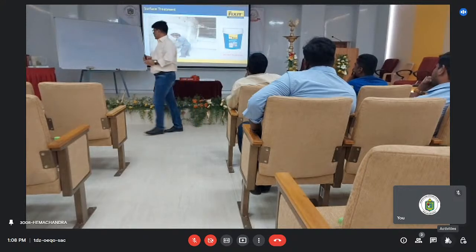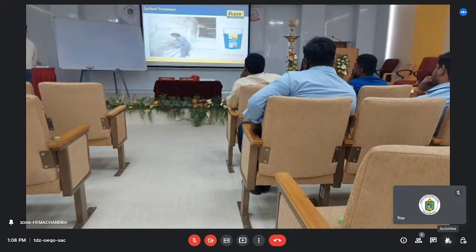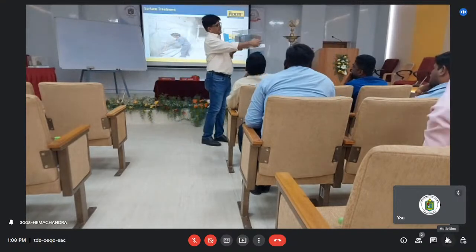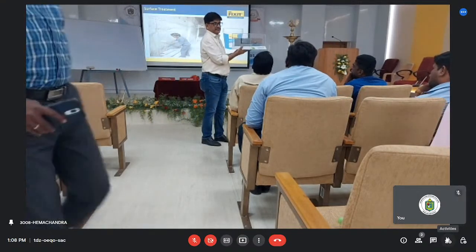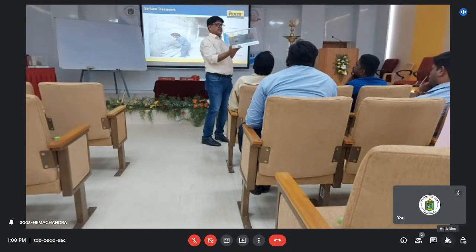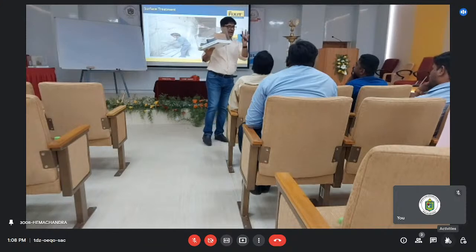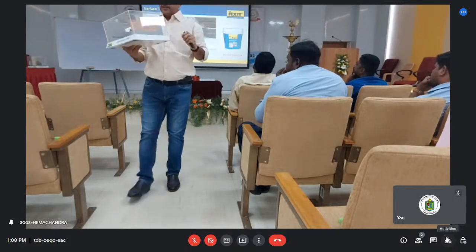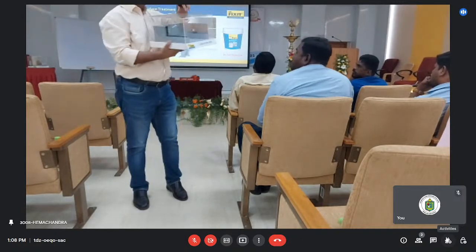Now in the construction joints, in some constructions, people provide an injection hose system. How many of you have seen this? During the construction itself, people provide this blue color. You can see this. This is called the injection hose system. So the injection hose system is already provided, and the junction boxes are already there, from where you can inject. That is the provision already given.